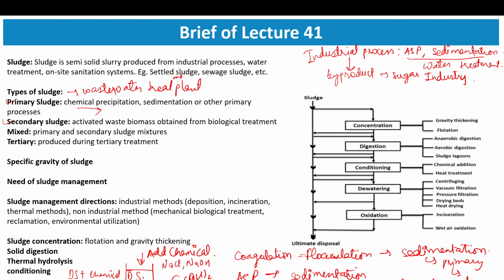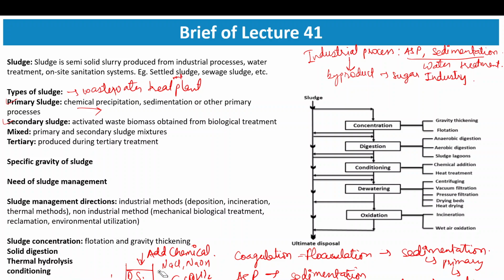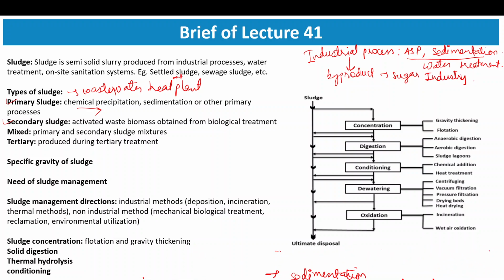Now, why do we need to remove these dissolved solids? Because they might have some toxicity. Say, for example, the dissolved solid is due to the presence of some heavy metals, including lead or chromium, etc. So if we want to remove these, we can add some chemicals such that they get converted into their non-soluble form, and hence it produces a precipitate: dissolved solid plus chemical.